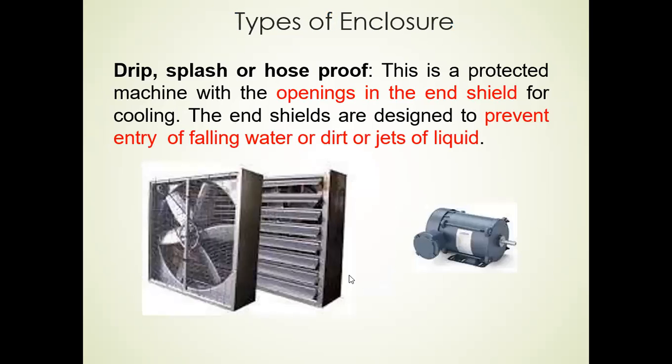Then drip, splash or hose proof. Here, a protected machine with the openings in the end shield for cooling. The end shields are designed to prevent entry of falling water, dirt or jets of liquid.